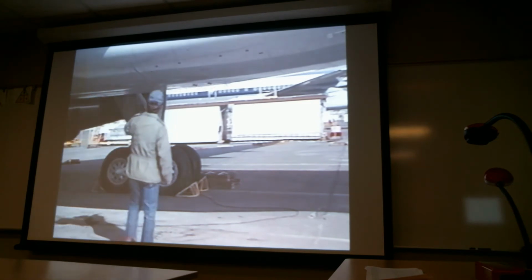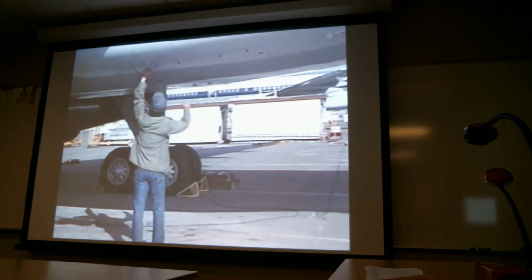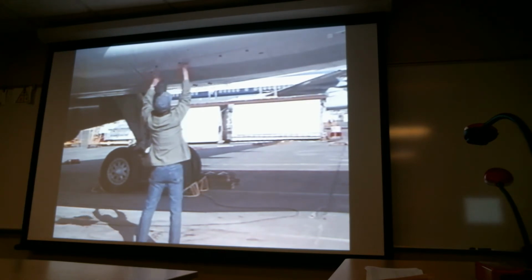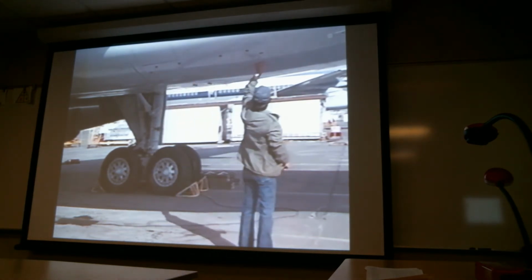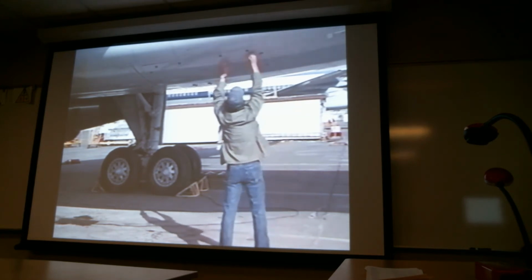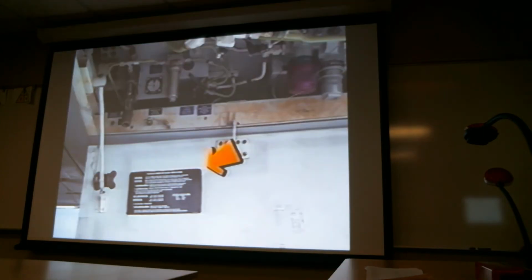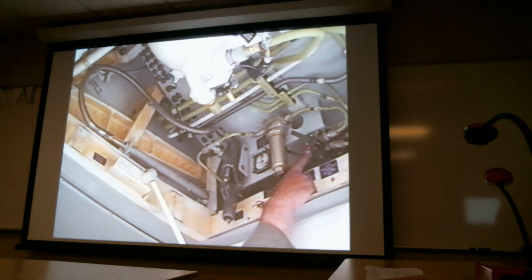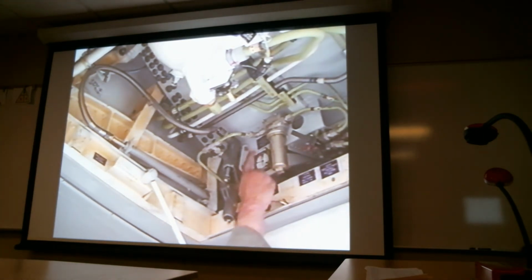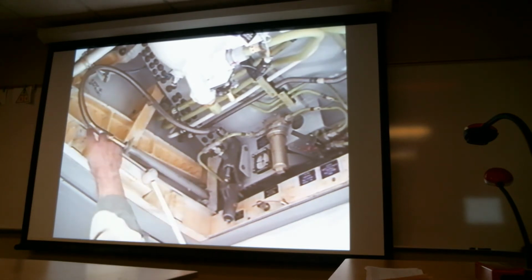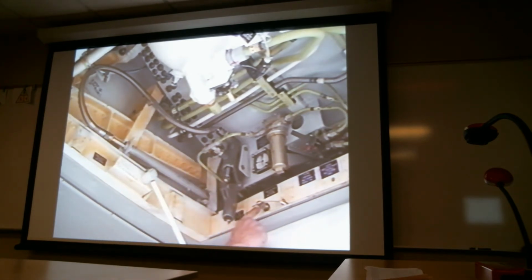The ground servicing station is located in the aft left wing-to-body fairing. Releasing the latches will allow access. Servicing instructions are located on the door. The hydraulic service station panel contains a four-way, four-position valve and switch, a remote quantity indicator, a hand pump and suction hose, a ground pressure fill port, and a filter unit.